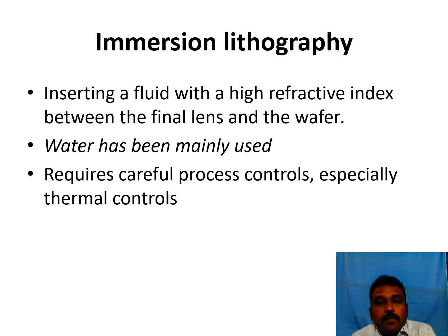And then the immersion lithography, as the name indicates, is inserting a fluid with a very high refractive index between the final lens and the wafer. So mostly we use water as a fluid. It requires careful process controls, especially thermal controls.